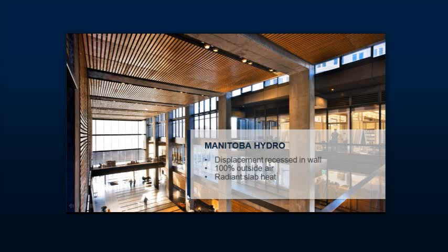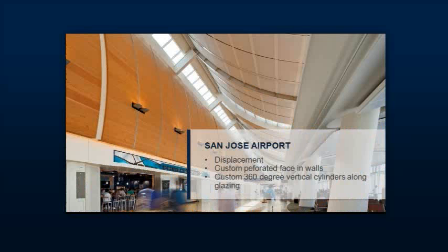Displacement ventilation. You can see it's incorporated in these vertical risers between the book shelves. This is a 180-degree round diffuser with the top part being covered by an acoustical face. So these are top fed. You could have fed these from the bottom or the back. You could have put shelves on them. I've seen them used in common areas of high schools where they're along the edge and they put their trophy cases on the top of them. There's all these different ways to incorporate in the building structure. But one thing you can easily get out of displacement is it's incredibly quiet.